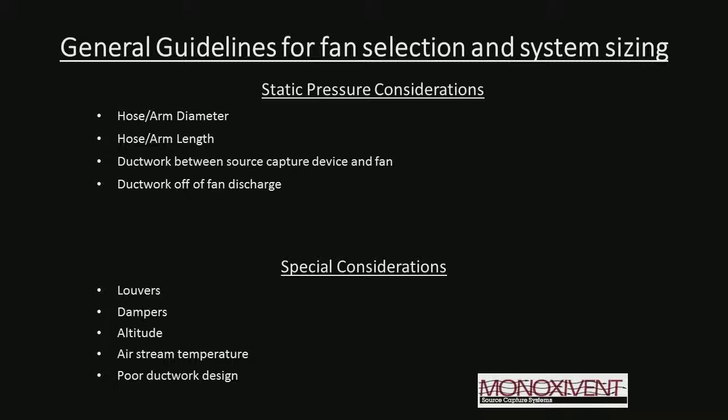Also, some poor duct design. If there are odd elbows or elbows that go against the grain, so to speak, those can add static pressure. It's called system effect. Bad duct design adds extra static pressure, which in turn adds more horsepower to the system.